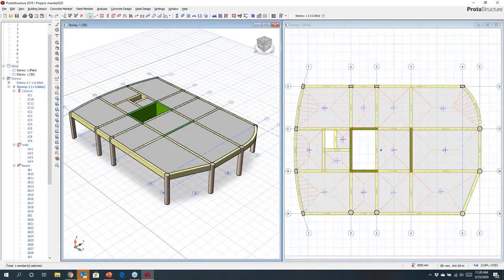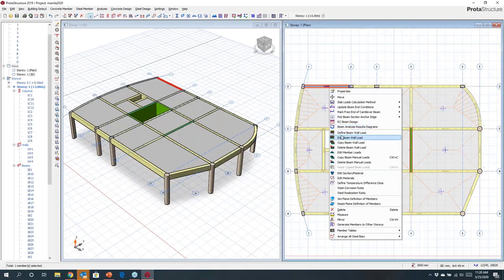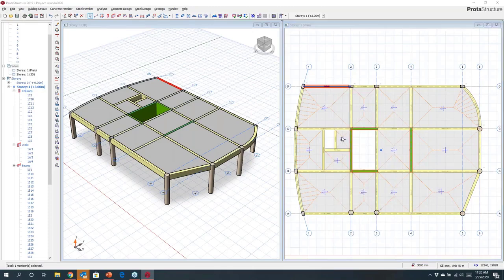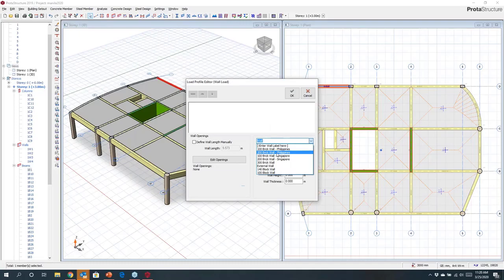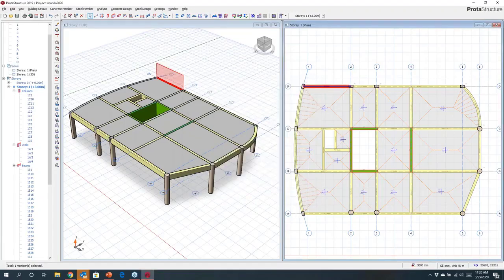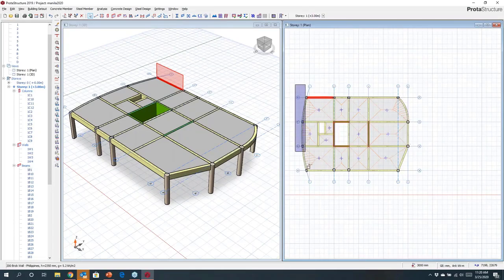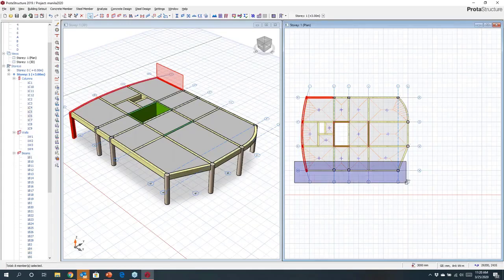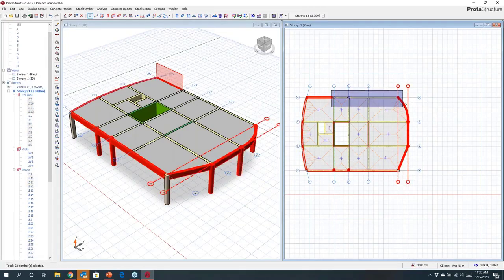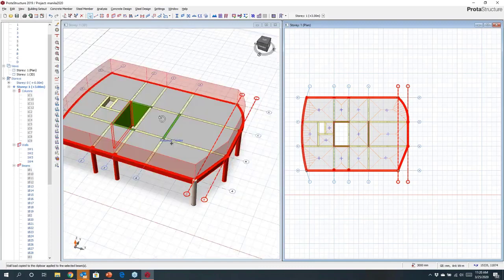Now you can work with this model to define other things. I may in here want to come in and put in things like brick wall loading, and you can come and pre-program maybe standard brick wall loads here. Okay, you can type in the height. Okay, and then that brick wall load's created on that member. Now these can easily be copied, so I can copy the beam wall load, and maybe I want to choose just to copy the external members there. Okay, and then we just paste it. So it's a very simple procedure for coming and setting up those loads around the periphery there.